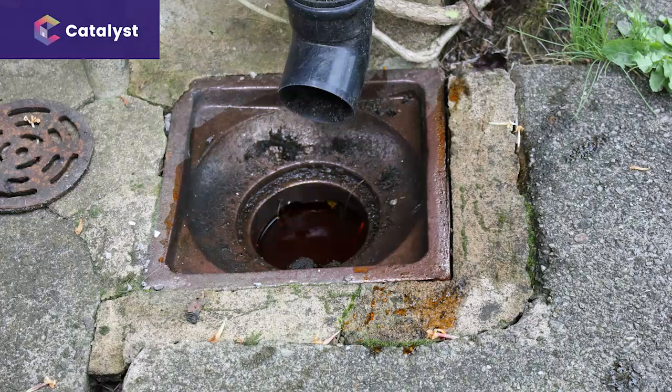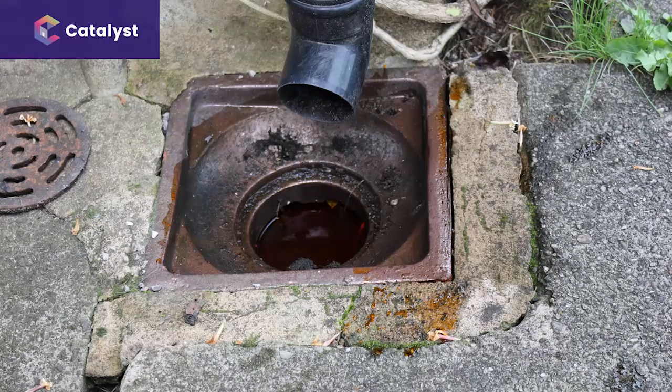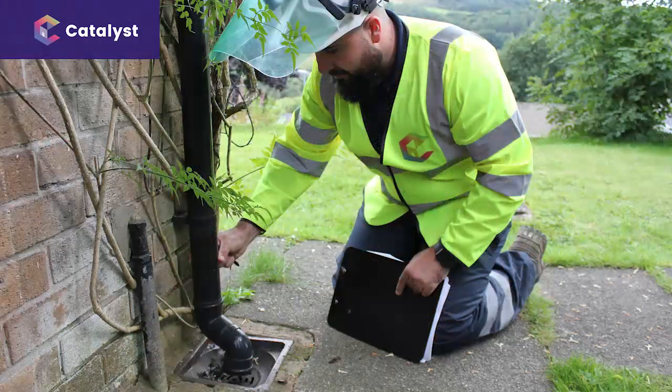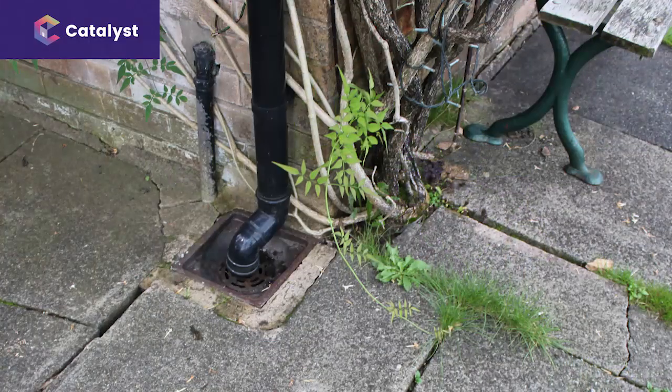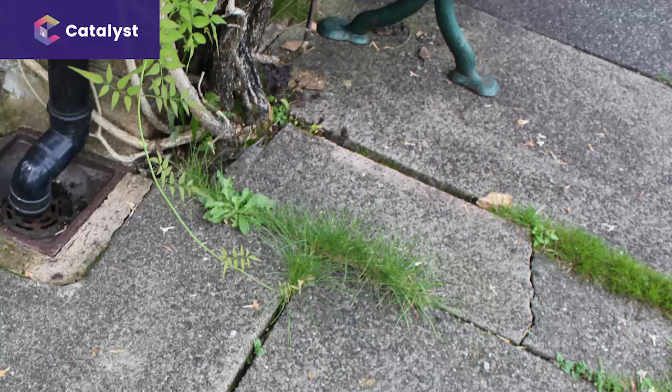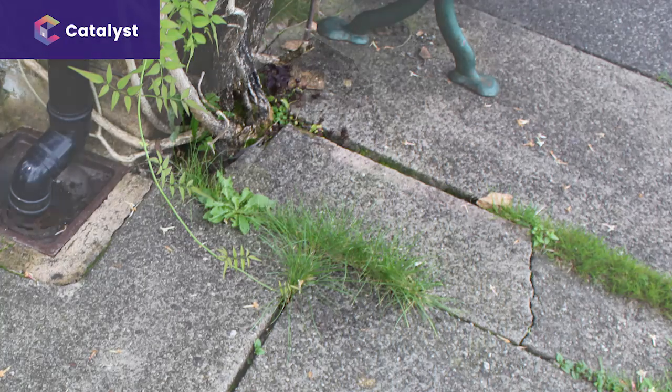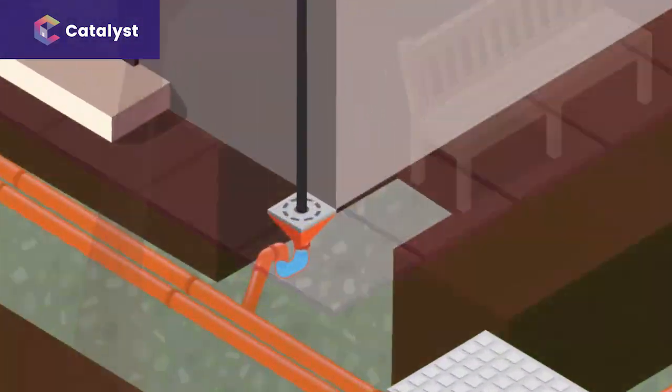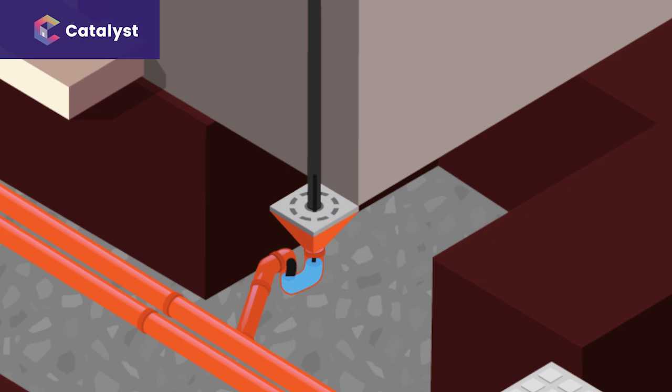The importance of water testing to check for leaks from sewer pipes is often also overlooked. If soil testing or a visual inspection indicates that the ground around a drain is unusually soft, a low-pressure water test should be considered. This is done by inflating an airbag in the section of pipe you want to check. You will need access to insert the airbag downstream and a visual on the water level upstream.